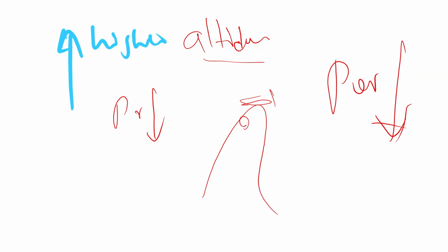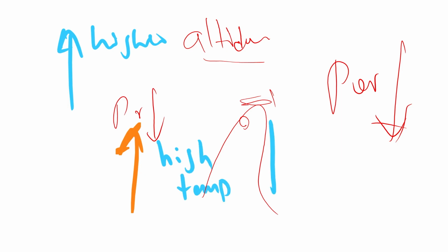So what are the other things that are going to happen? Let's say what happens if the temperature increases? If we have a high temperature, what happens? High temperature means again the performance will decrease. Performance will decrease with an increase in temperature. You can logically think: if the temperature is high, the density will be low, right? Density decreases, which means less air. So we need to put in more engine force to create the thrust and all the things. So that's causing the performance to degrade, right?